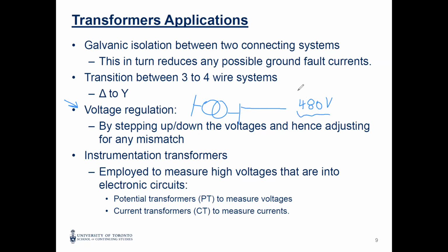This voltage, you need to have this certain voltage in your factory, for example, 480 volt, because all your motors and systems depend on this voltage. Okay, so during the system or inside the system, the voltage can reach 485 volt because of the changes in the voltage here in the transmission.